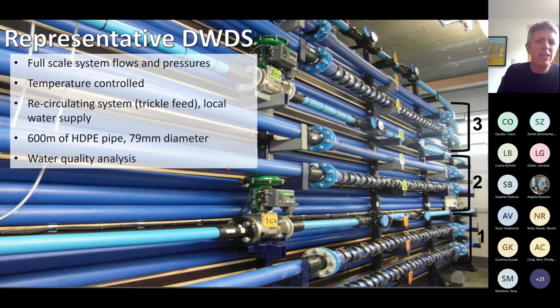The next question is really, how do we study these? I've said it's really hard to access buried pipes, to take samples of the biofilms and have a look at them, yet the pipe environment is really complex and unique. So what we built at Sheffield over the years is a very unique international facility. It comprises notionally 4-inch, but actually 80 mm internal diameter MDPE or HDPE pipe, very common of what the water companies put in the ground now. It's coiled up in our lab, although it's still a big room full.